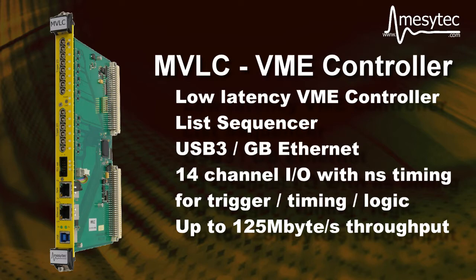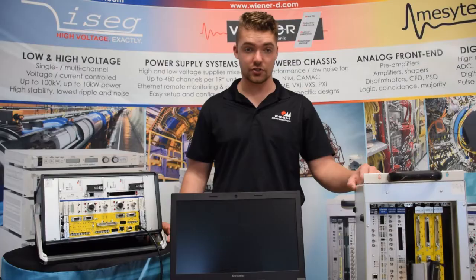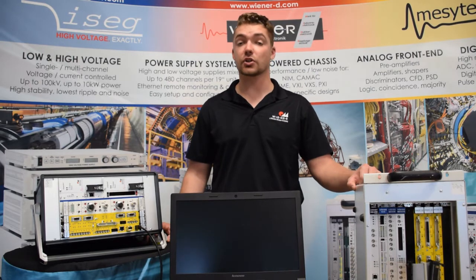Moving on to the VME master controller. VME data collection happens nearly in real time with very low latency by using interrupt-triggered list sequencers in the VME master controller. For the best performance, we suggest the Mesytec MVLC controller with USB 3 and Gigabit Ethernet connection, which has an overall data rate between 60 and 125 megabytes per second. Further, the MVLC is outfitted with a flexible triggering logic unit with 14 IOs, which can be configured as trigger inputs and outputs or gate generators, all with 1 nanosecond resolution. We also offer the VM-USB as a low-cost variant option.